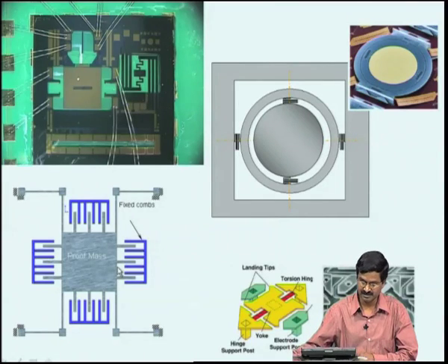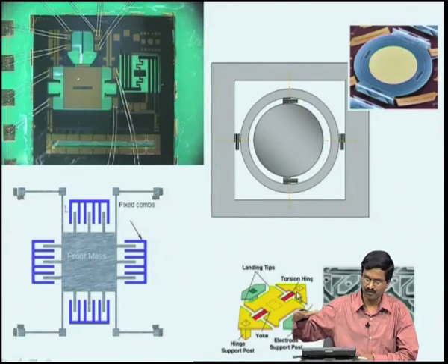Below here we have a proof mass suspended by again beams, here 4 sets of L-shaped beams, and this one acts like a gyroscope, which we will discuss in the next lecture. But here again we have a vibrating mass which is connected to these beams, which are characterized by springs. And in the lower left corner, we have this torsion mirror which twists about this red colored beam on either side. This yellow part, the H shaped structure, can twist about this axis. That also is like a vibratory motion, because something will be tilting back and forth.